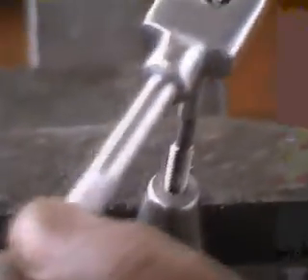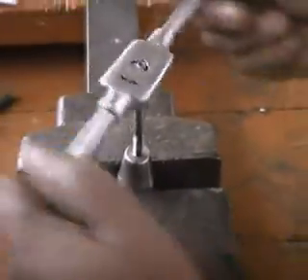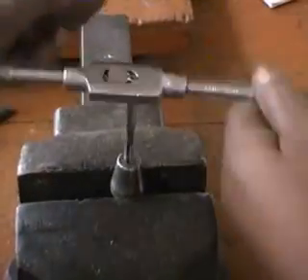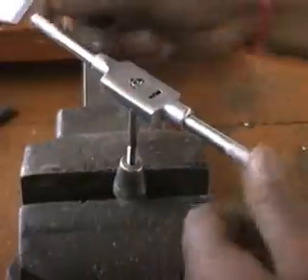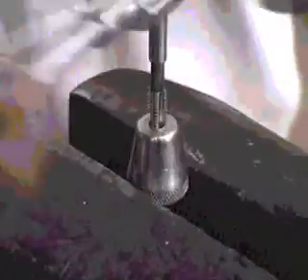This is a job that has to have internal threads made in it. We rotate one complete round forward and then half a round back. Whatever material gets cut in the first forward rotation gets removed in the half reverse turn, so the tap does not get stuck. So we take out the first tap and put in the second tap. This is the second tap at work. You can see we are moving one forward and half backward.